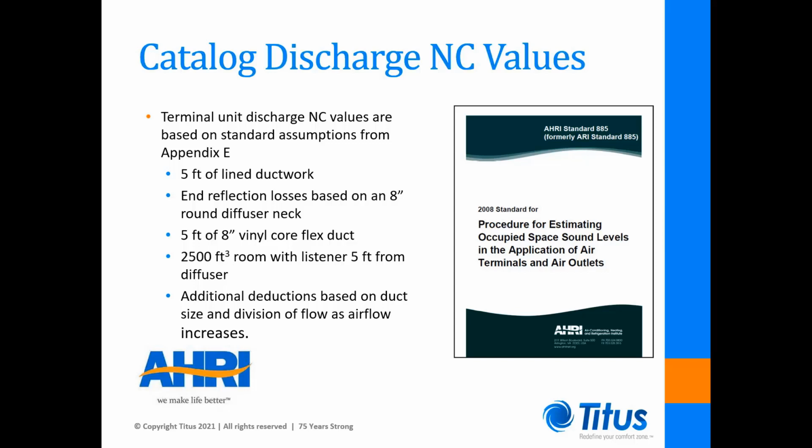Then there's end reflection based on an outlet with an 8 inch round neck. Then there's flex duct assumed to be 8 inch round and 5 foot long. Then there's a space effect based on a 2,400 cubic foot room with the listener 5 feet away from the closest outlet. Finally, there's a sound power division based on the number of rooms being served.